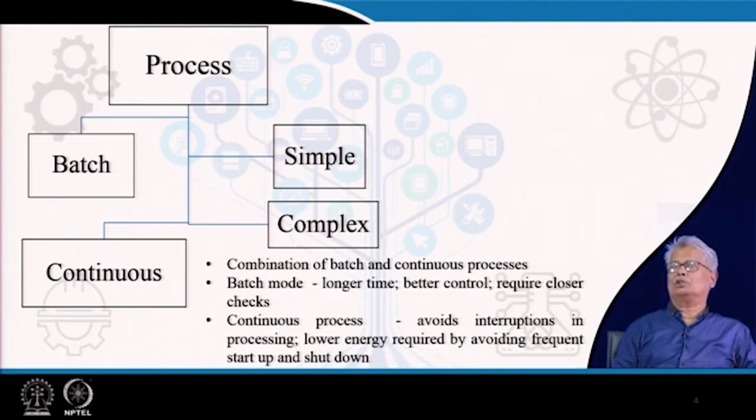So, one thing is true, that in case of any batch process there will be startups and shutdowns, and you also have to remember that in any batch operation the entire feed material of the batch is normally fed to the batch equipment in one shot. So, if I have a processing system for 10 tons per day, and if I decide that I will be doing it in a batch, my batch should be capable of holding all the 10 tons of material together.